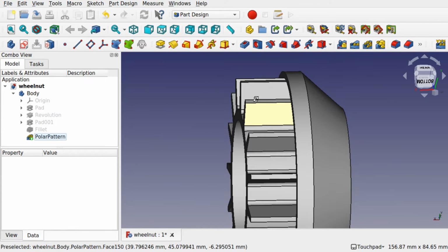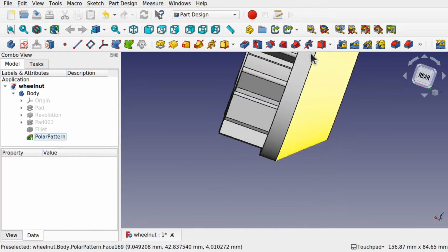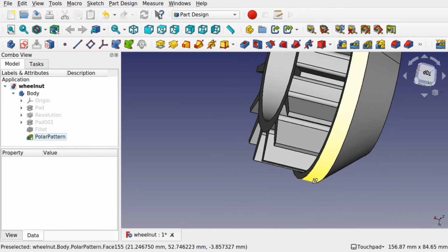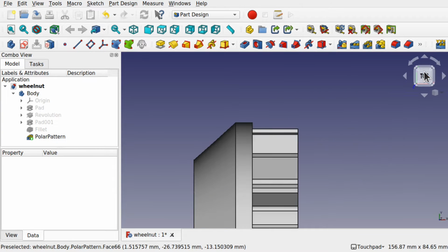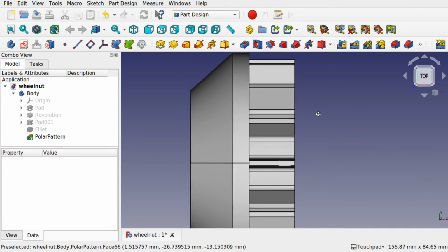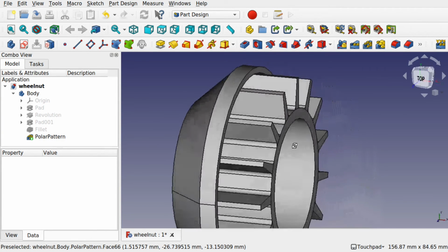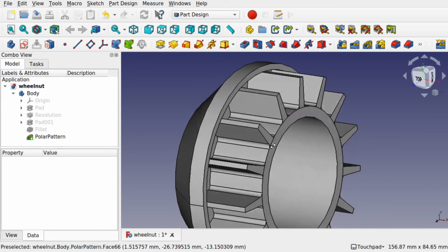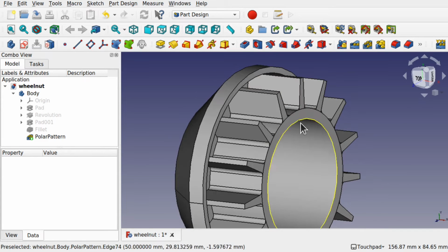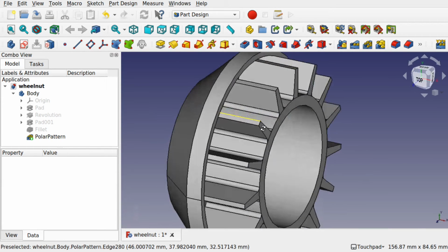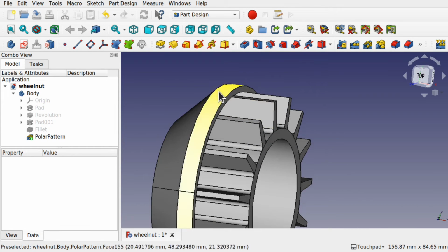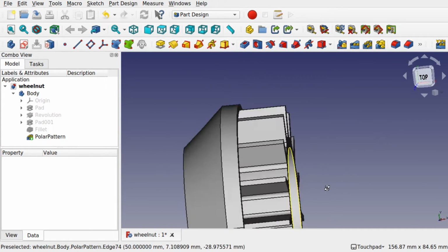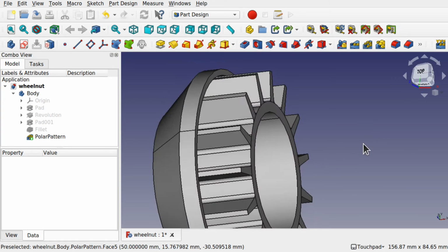So now I'm going to create a sketch in here. So I'm going to come round to the top. And what I need to do is pick some geometry from here to import. So first of all, I'm going to make sure there's nothing selected because I haven't got anything to actually hang this geometry on. I want to make a profile for the groove. So there's nothing really that I can hang this on. So I'm going to hang it onto the base plane.